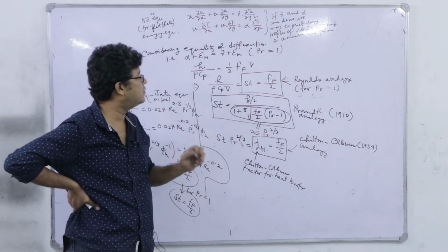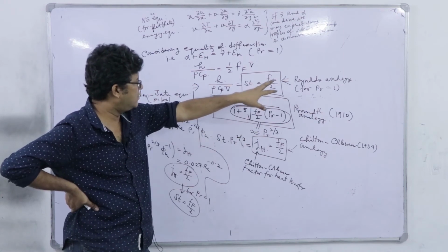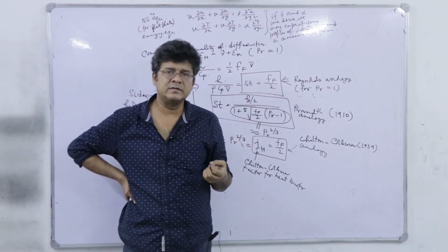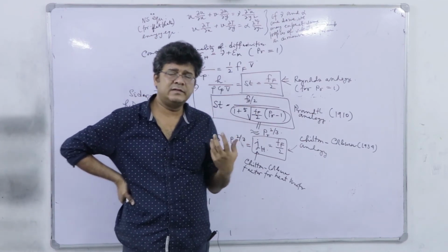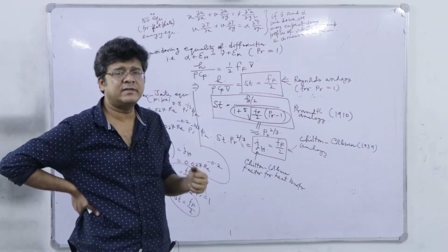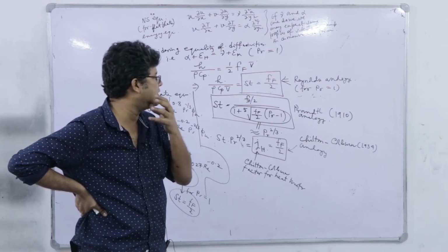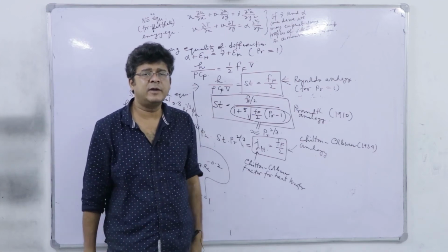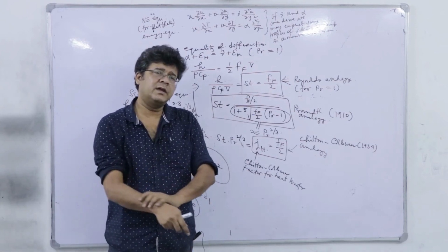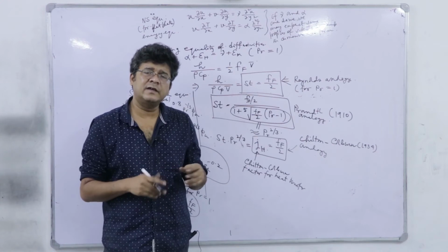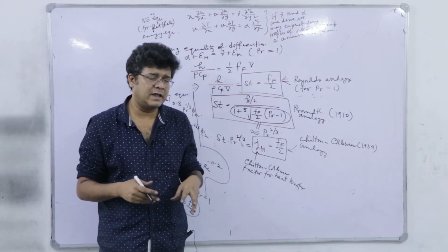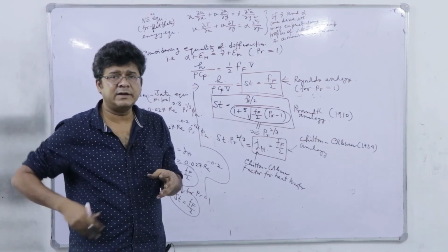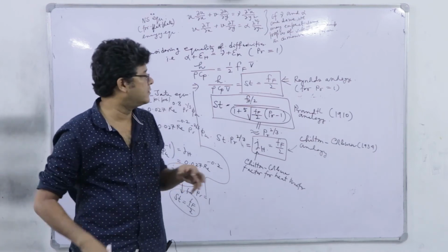analogy will be majorly used for, and actually more than its use, it has got its theoretical importance, right, because if I need an accurate measurement, I will go for dimensional correlations, conducting experiment, and therefrom we can get the expression of h, in terms of Nusselt number mostly, as a function of Reynolds number, Prandtl number and pertinent other dimensionless groups of the system.